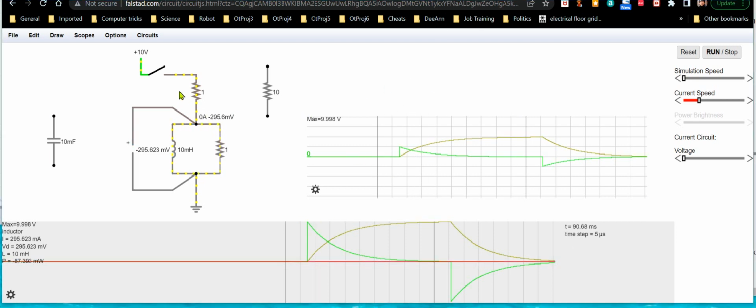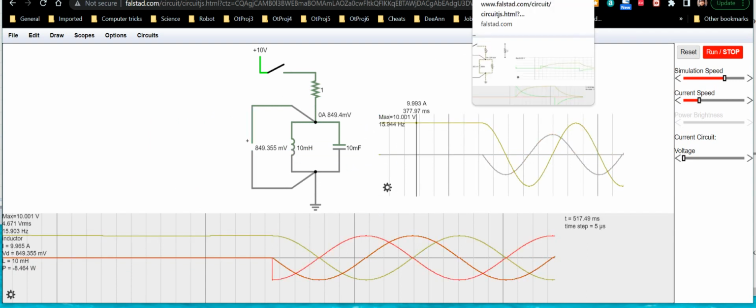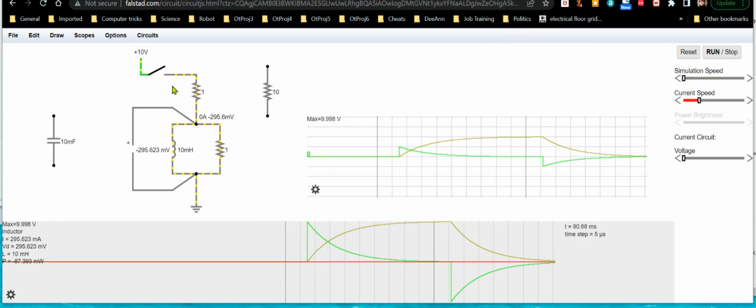And just like I said with inductors, if I were to flip this to a negative voltage source, all these waveforms would reverse, because again, this is DC right now, but when we get to a tank circuit, it'll be an AC situation that you'll see take place, because this is basically a way of taking a DC signal and turning it into an AC signal, in a loose kind of sense.